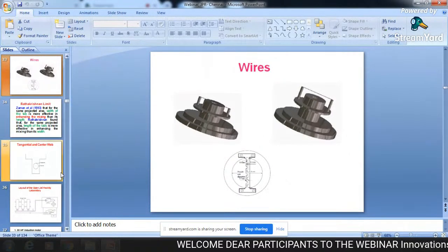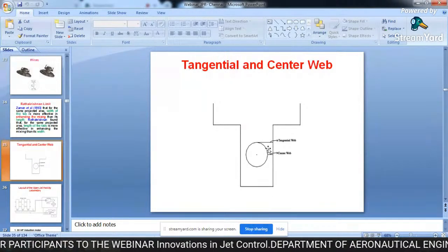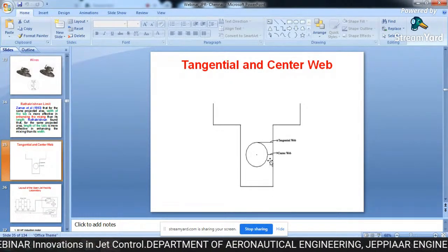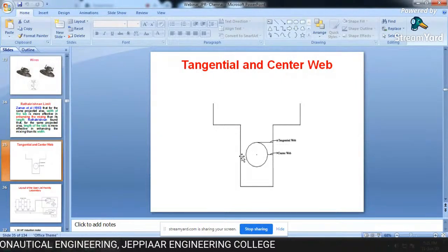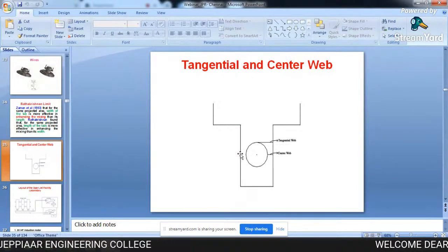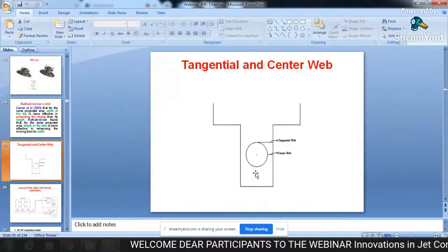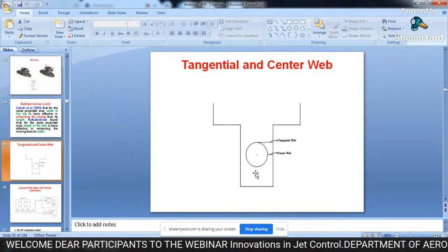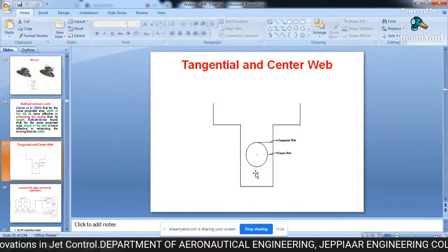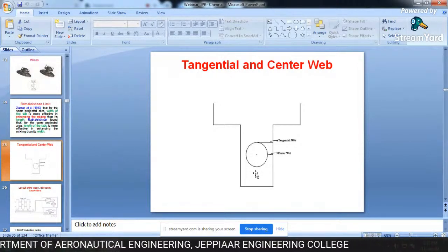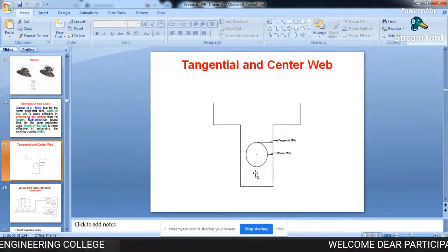Now I am going to the perforated tab. The thing is that we are accounting for the thrust loss, and as you can see here, two limbs are there, because when we created it, I will show you in detail also. These limbs were capable of creating small vortices. Once small vortices are created, because literature says that if small vortices are there, the mixing enhancement capability is more efficient, keeping all that in mind, we did this research.